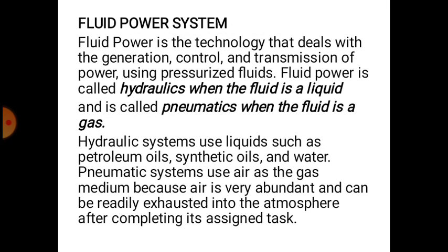High pressure fluids, both liquids and gases, can be used to transmit power. So here we are going to use high pressure fluids to transmit the power from one point of source to the point of utilization. So it is from pump to the actuators, from point of source to the point of utilization, which in turn can be used to produce rotary or linear motions. Another special application of fluid power is to apply a force onto an object and release the force. Though it is possible to apply forces through some mechanical means, fluid power is the most convenient way. Fluid power systems that use liquids as working medium are termed as hydraulic systems. Fluid power systems that use gases are termed as pneumatic systems. So fluid power refers to the branch of engineering that deals with the use of high pressure fluids within confined areas to generate, control and transmit power.